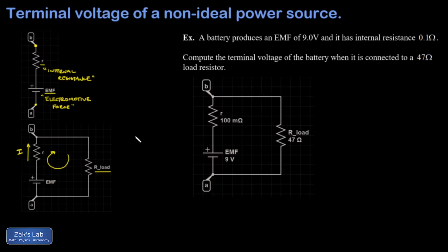So the way we formalize these voltage differences is I would take a path from one node to the other, and I'll say the potential at A plus the EMF, as I'm traversing this path up the left branch of the circuit, I just went up by a voltage equal to the EMF, minus IR. So I applied Ohm's Law there. I said V equals IR for the resistor, and that was a voltage drop. So VA plus the EMF minus IR is equal to VB. This allows us to express VB minus VA as the EMF minus IR.